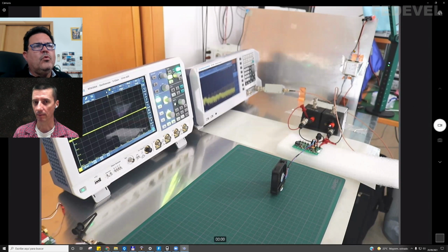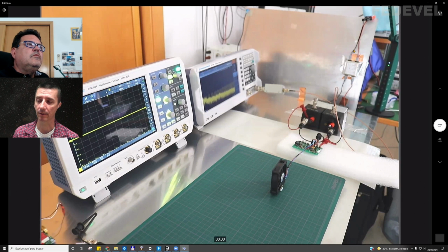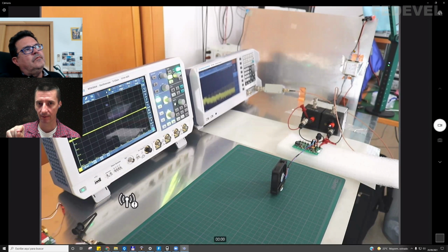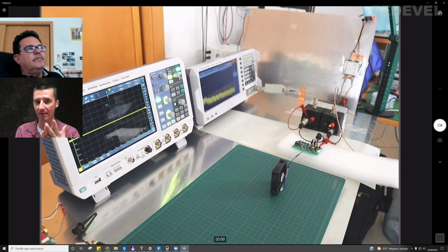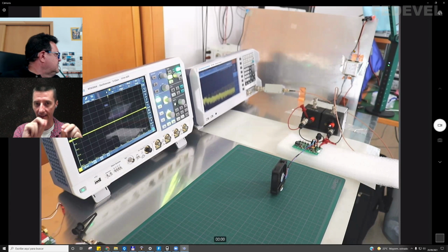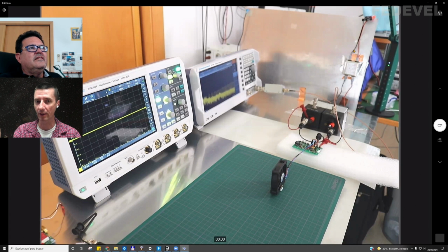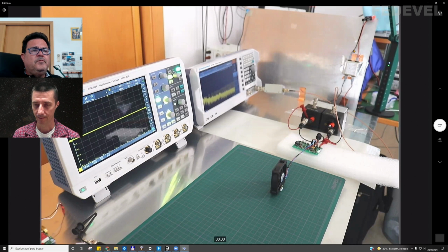Okay, so I would like to add that some power supplies actually have a third output, which is basically the chassis or ground of the instrument. So you have like 3 outputs from the power supply, the 0, plus, and then the ground. And sometimes you would like to connect the ground together with the 0, and sometimes not. So in this case, it is not connected. It's floating. The ground terminal is floating relative to the earth system or the metal plate reference.